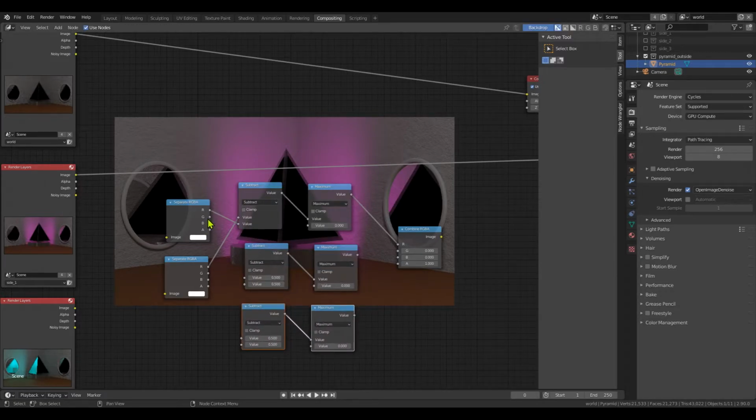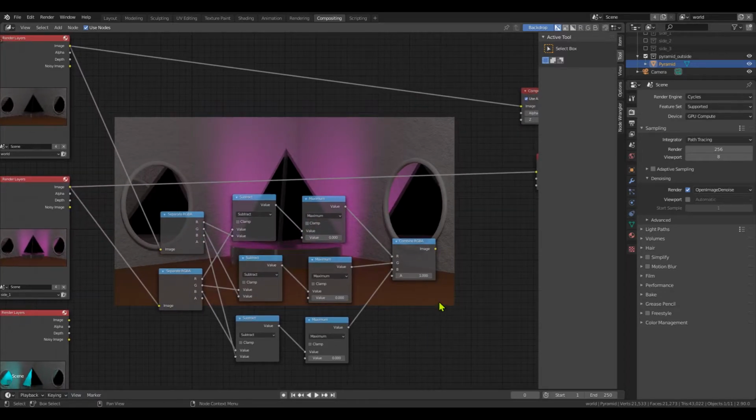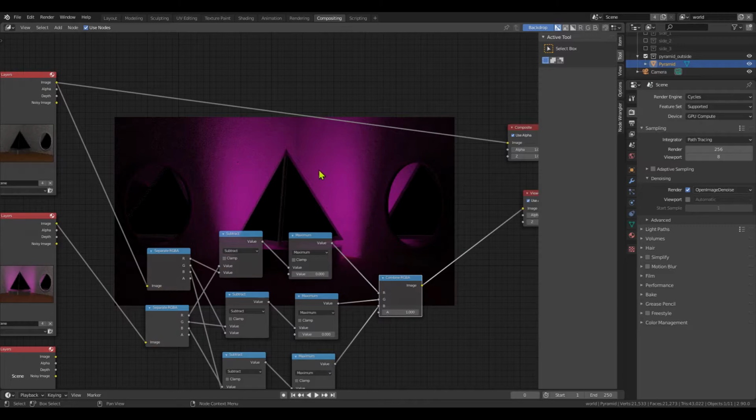And again, we subtract the upper image from the lower image in both green and in blue. And afterwards, we have to connect this to the combine. Green and blue. And we connect this to the images. The upper one is a dark image with all sides closed, and the lower one is the image where side 1 is open. And with Node Wrangler enabled, we can Control-Shift-Left-click to connect this with the viewer, and we see that this is the difference we would expect.